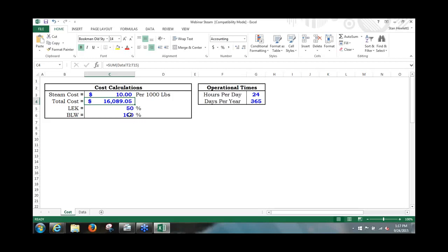But we have different options in here. We have leak and blow through, and we have certain percentages associated with this. Now, a lot of people don't like using 100% because they say that it's not fully blown through. So they would actually use either 90% or 80% blowing through. That makes the numbers a little bit more conservative. Same thing with leak. We give you a drop-down box to choose from and pick whatever percentage you think is relevant for your steam trap survey. So I'm going to use the 80 and 40% rule.